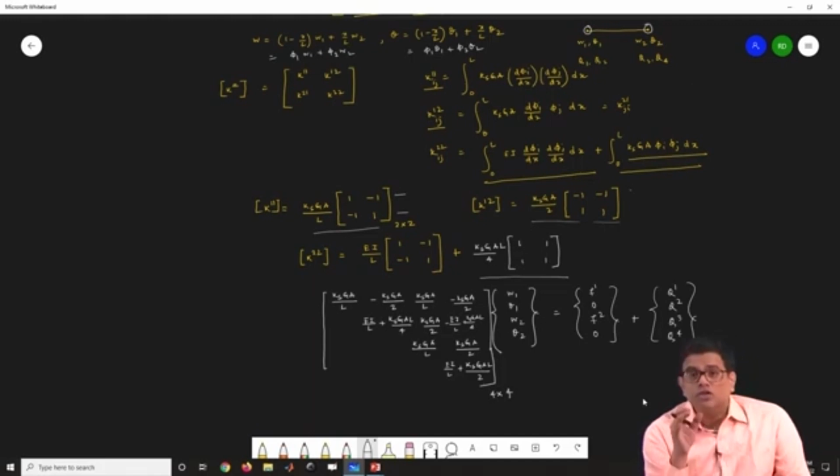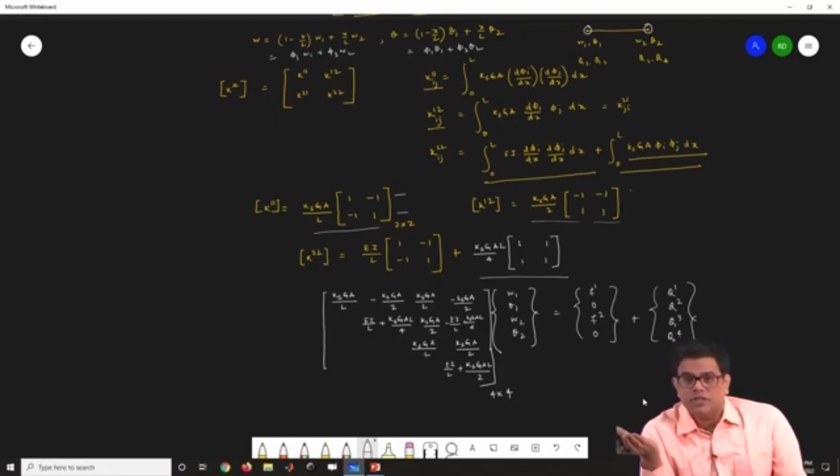Essentially, when the beam thickness reduces, your finite element solution locks. So what does locking mean? Locking means that meshes are not capable enough of representing the deformations or the solutions.